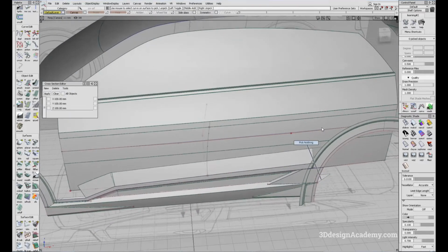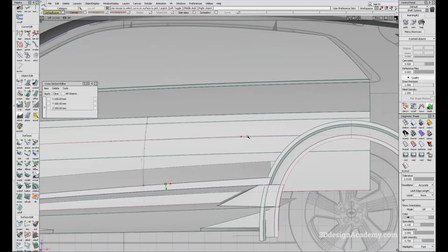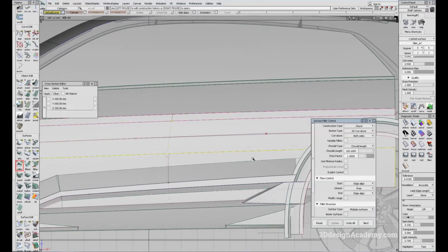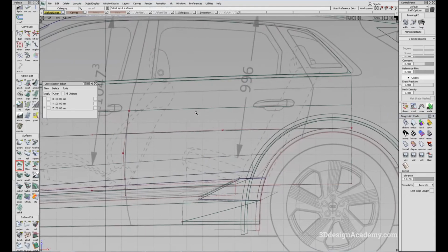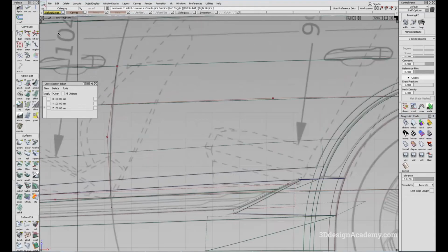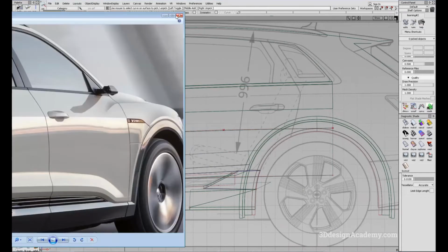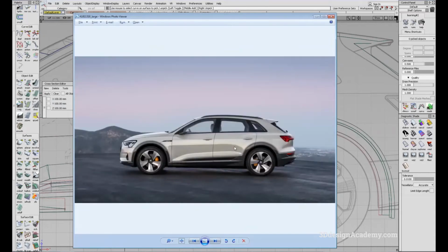where the highlight is not doing something funny. Next thing I'm going to do is add a fender, or start of a fender, over on this side. So in order to do that, I'm first of all going to undo this fillet. And I'm going to add a curve. Actually, before we do this, let's check the shape of the highlight.